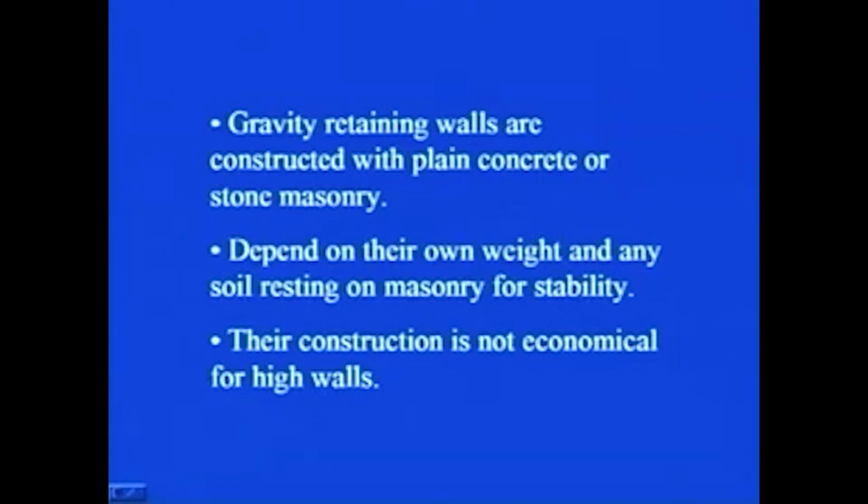So, you can imagine that if you have to retain the soil and go in for gravity walls, how heavy they will be in their weight to gain that particular stability. Their construction is not economical for high walls, because as soon as you increase the height of the wall, since there is no reinforcement, the masonry or plain concrete required will be quite high, and so its weight. So this becomes a very bulky structure, and it leads to uneconomy.